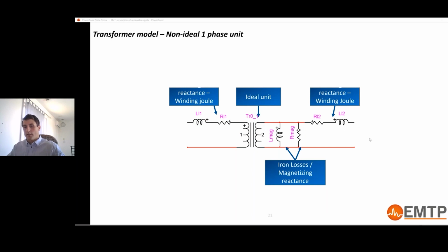You connect on one side of the transformer, you apply a voltage source, and the secondary is disconnected. So you have the current going like this. But because this resistance is much larger than this one, you can approximate that there is no impedance here and that all the losses are due to this resistance. And so then it's basic, you can calculate directly what is the resistance here.